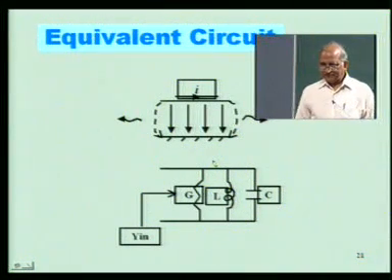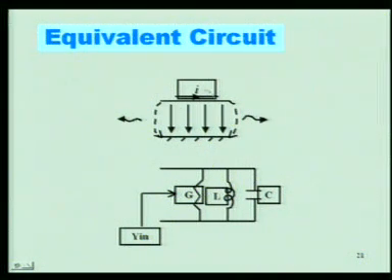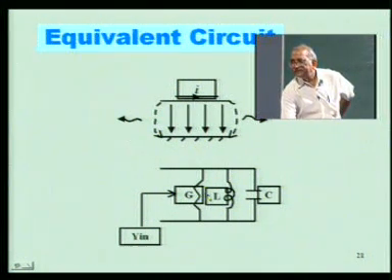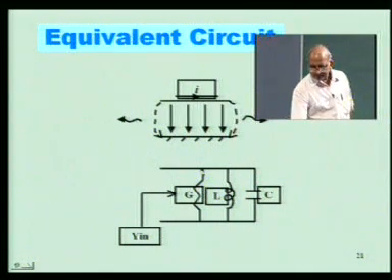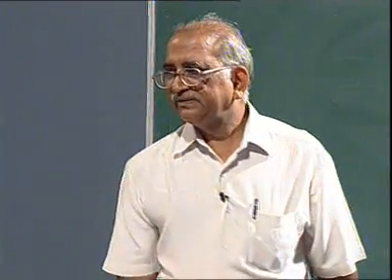And the equivalent circuit now for a patch with this type of electric field distribution between the patch and ground plane: the current on the patch metallization will be like this, and these are the fringing fields shown over here which account for the radiation. So, the equivalent circuit for this one can be put in terms of a parallel combination of equivalent L, C and G. This G accounts for the power radiated. So, if one can find out the equivalent L, C and G, one can calculate the input impedance. Okay. So, it is a parallel resonant circuit.